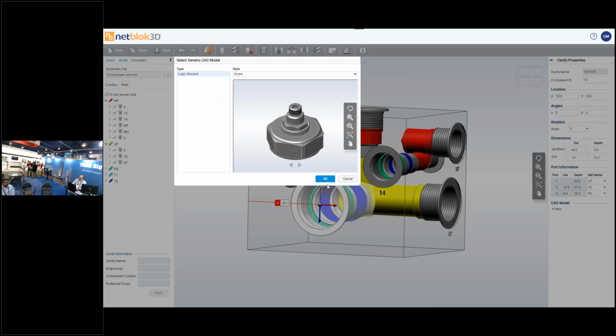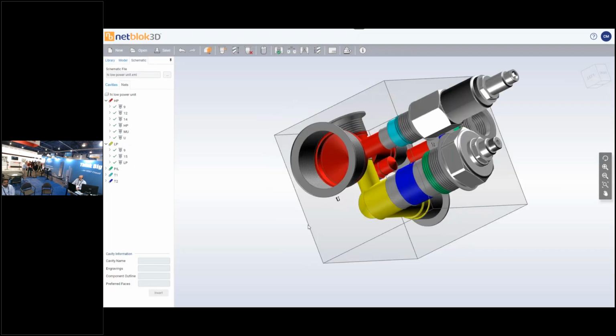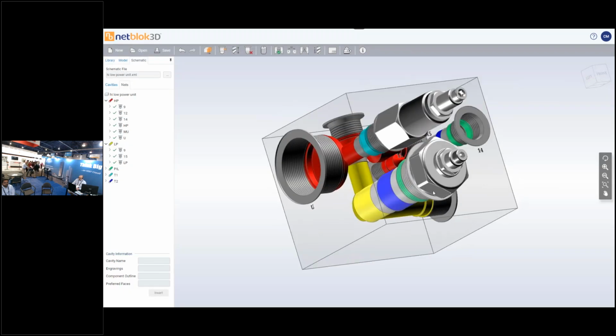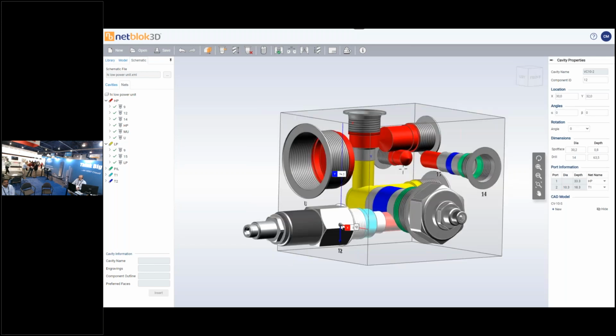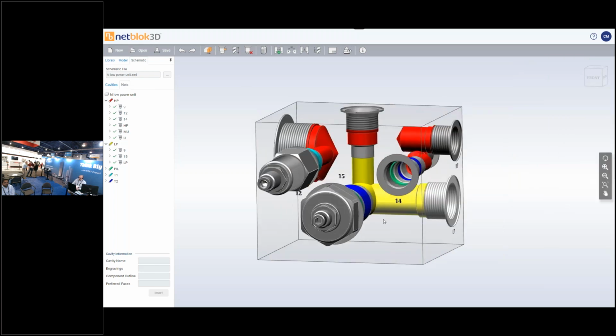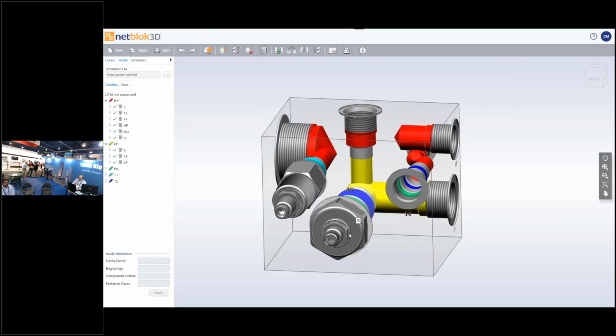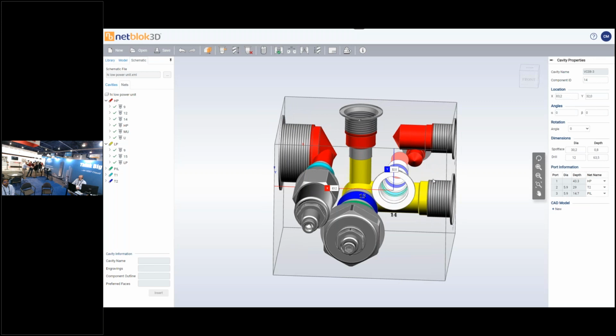That's not really important. And of course, if you just drag the cavity in a different position, the 3D model will just follow. By using undo, Control Z, you will be able to undo the previous operation. So looks good. I can compact a bit more my block. This was a sequencing valve, so let me add a new sequencing valve.